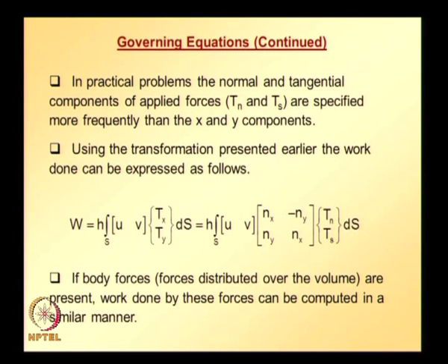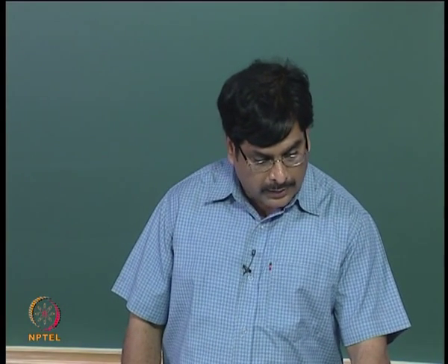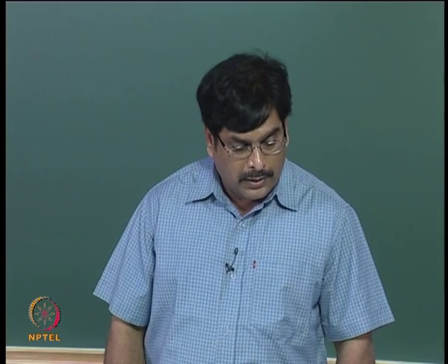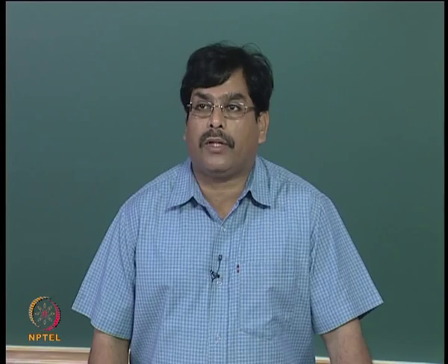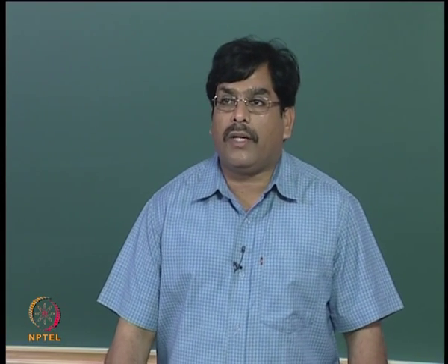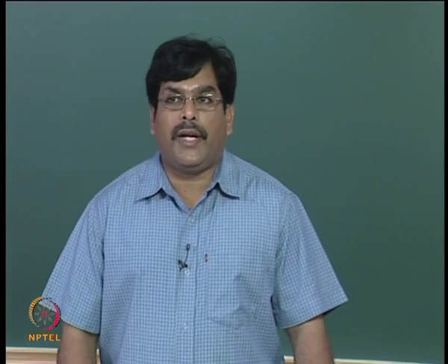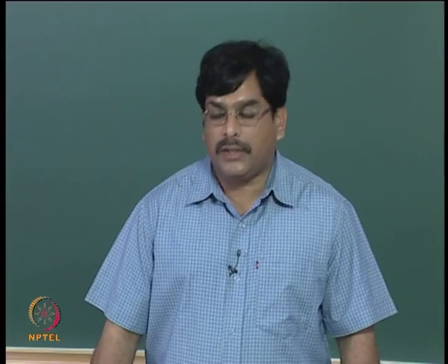So, now we need to verify whether the functional that is given, that is strain energy minus work done by the applied forces, is the correct functional for a 2-dimensional elastic problem or not. To verify that the potential energy functional is appropriate for plane stress and plane strain problems, we must show that the governing differential equations are recovered by setting the variation of Pi p equal to 0.